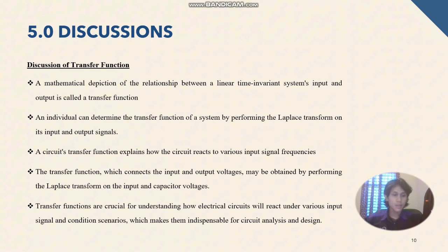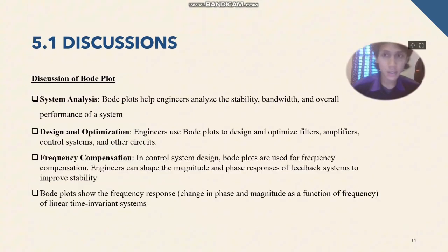They are widely employed in signal processing, control systems, and other branches of electrical systems. Next, for the last one is a discussion of Bode plots. System analysis: Bode plots help engineers analyze the stability, bandwidth, and overall performance of a system. They can identify resonance frequencies, gain margin, and phase margin, which are crucial for ensuring the system operates as desired without instability or excessive distortion.